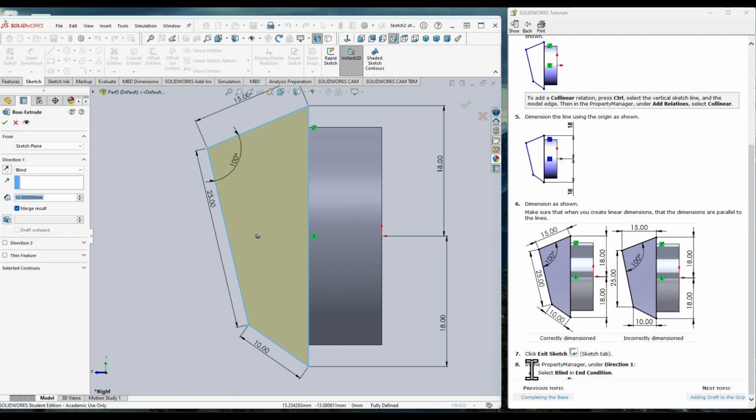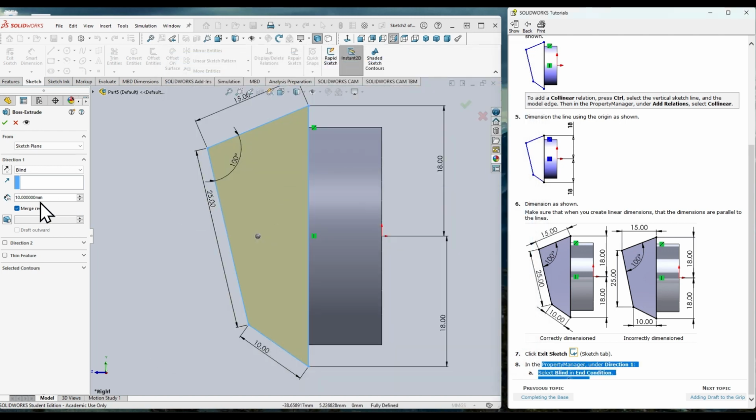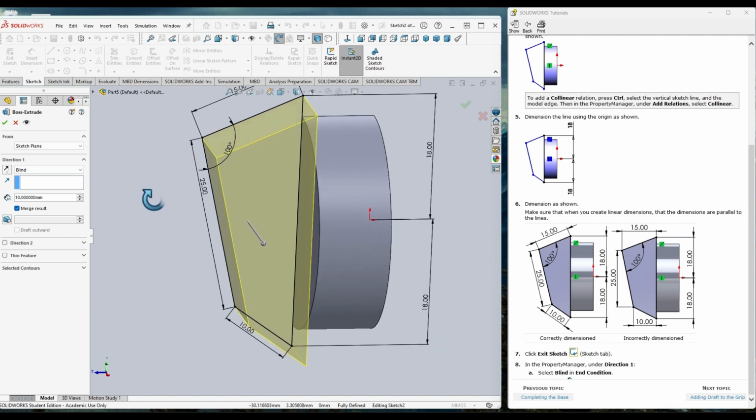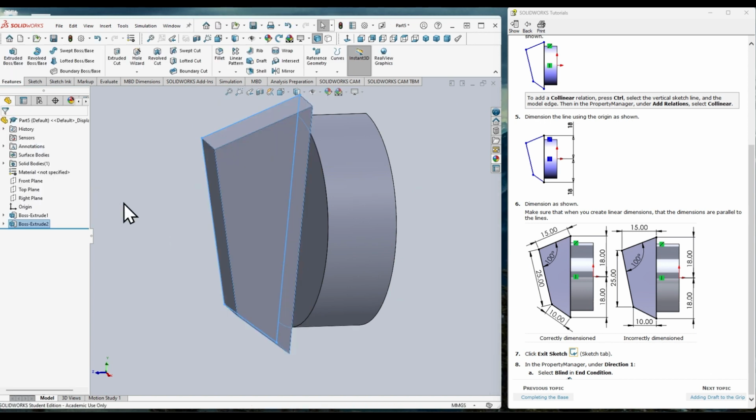And this is a part that is cut off in the instructions, and I always have to try to highlight it and open Word to see what it says to paste it. So it wants us to set it to a depth of 5. So just like before, because we did everything in the right order, it automatically went into the Boss Extrude tool. But now we are going to set this to 5 millimeters and then hit the check mark.